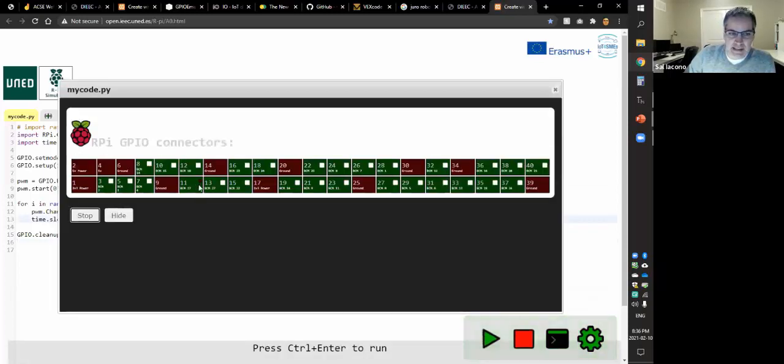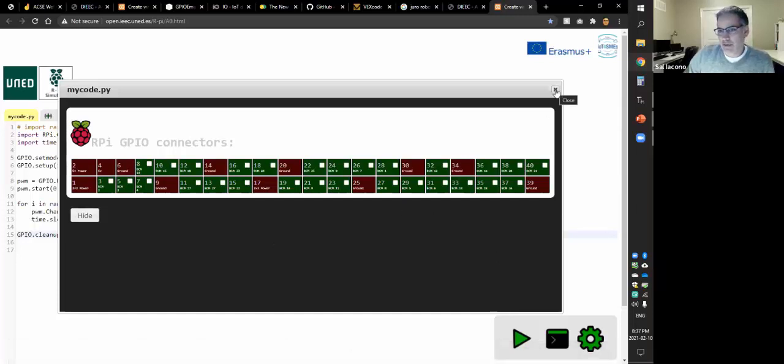Now you see it looks like an LED. It's blinking slowly. I don't know how well this shows up over Zoom, over sharing screen, but it's slowly increasing its rate of blinking. To the point where once we get near 100% duty cycle, the light will be virtually on constantly. You can stop it early if you need to. And there it's at 100, and then it stops. When it stops, it just reverts back to default. Okay, so there's the idea of using a PWM.